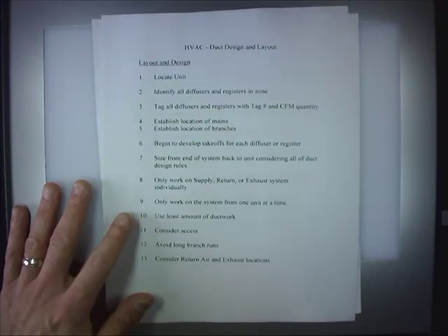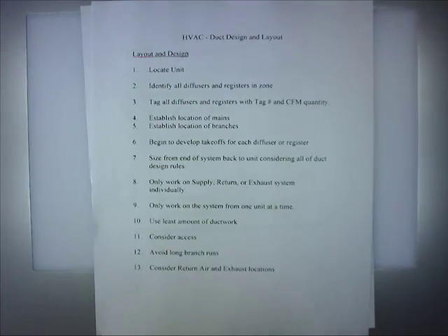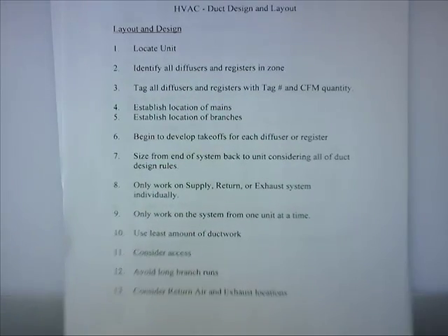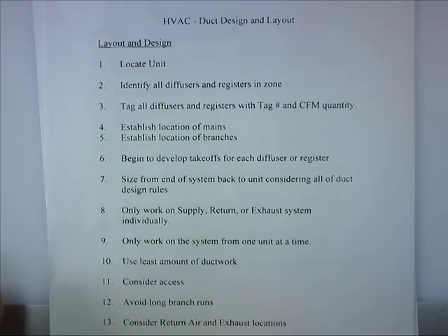Alright, so some of this is going to be a review from the preliminary ductwork layout the other day. So the very first thing, if you're going to do a ductwork layout, is you need to figure out where your unit is. You have to know where the ductwork is going to and where it's going to go back to for the return air.